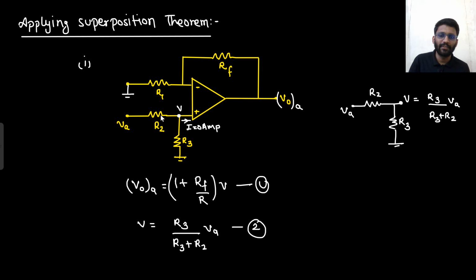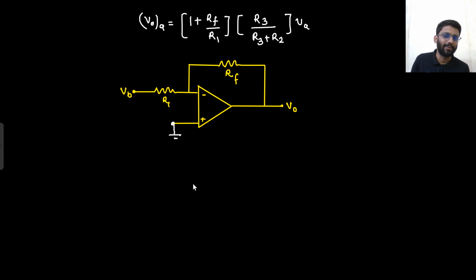Look, what was the scene? This was the circuit. I short circuited VA. If I short circuit VA, R2 and R3 will come in parallel, but R2 and R3 have 0 ampere current. If both have 0 ampere current, that means they will give 0 voltage drop. So here the voltage drop was ground, and this ground will carry here and become ground only. So this V positive node has become ground. This node has become ground. Now if this is grounded, then this will also be grounded.